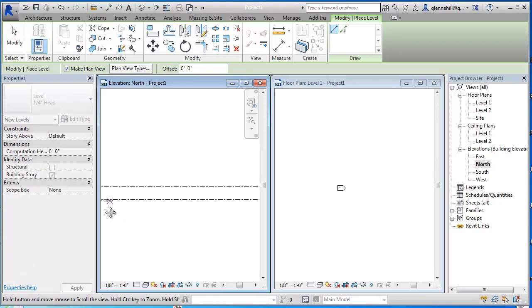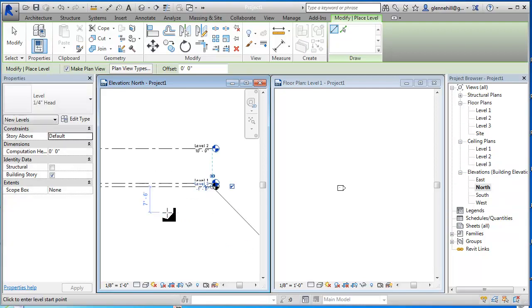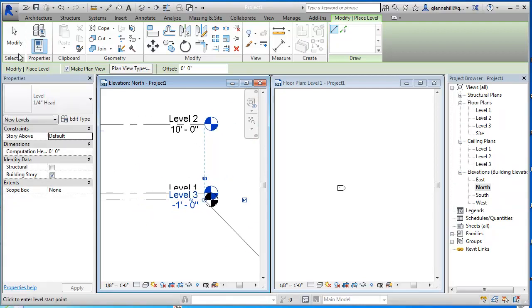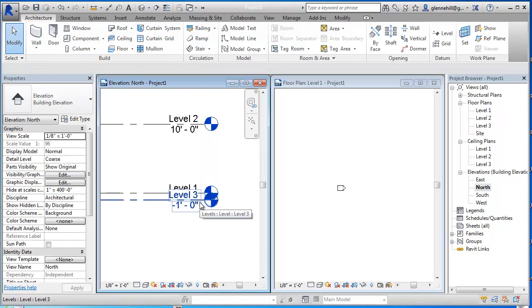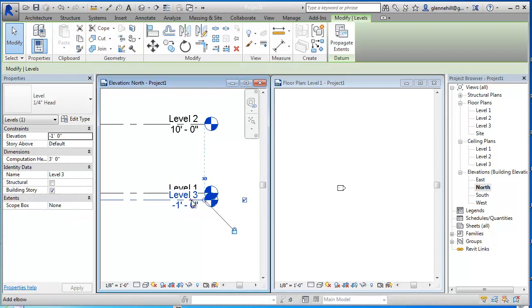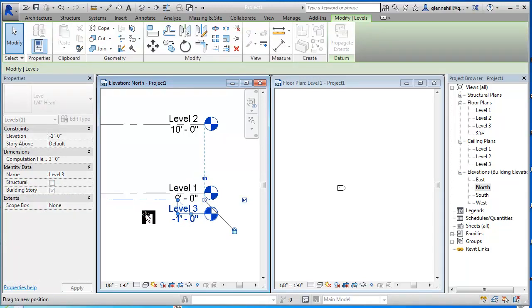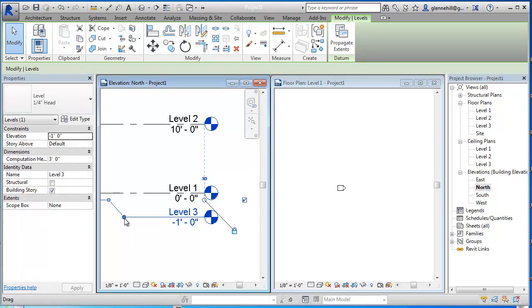level 1. And the reason I'm doing that is because, as a general rule, most building codes in cities require that your first floor finish, the finished first floor, be at least 1 foot above curb. That's to prevent flooding, as a general rule. In other places, it may even be greater than that, but most of the places that I'm familiar with, it's at least 1 foot. Lubbock, for instance, is 1 foot.